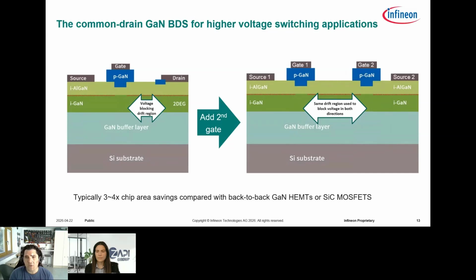And I think that we will probably find that any of us that go out and buy a new electric vehicle in 5 years, it probably is going to have bidirectional switches, GaN BDS based onboard chargers. The momentum's already there. But that being said, the T-type traction inverter or the current source inverter could come along really fast and surprise us all.